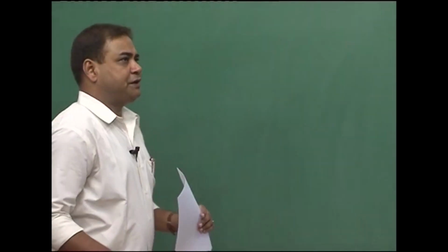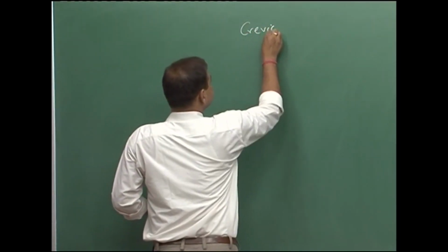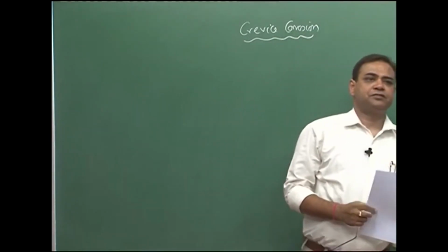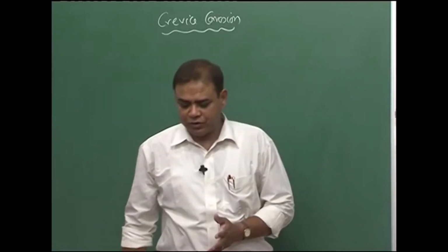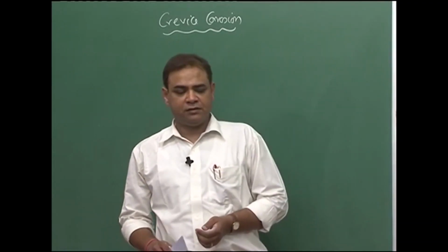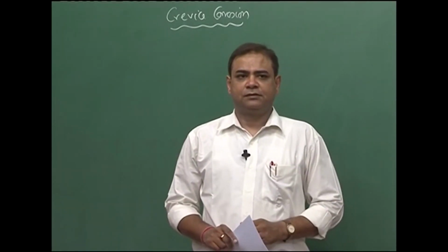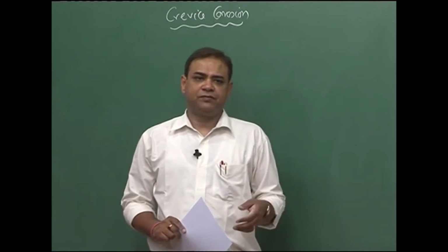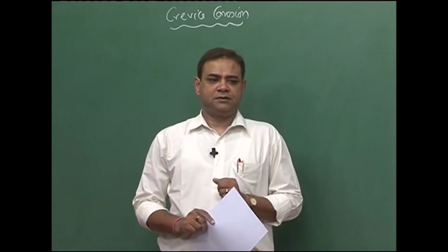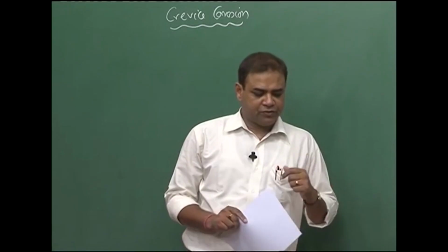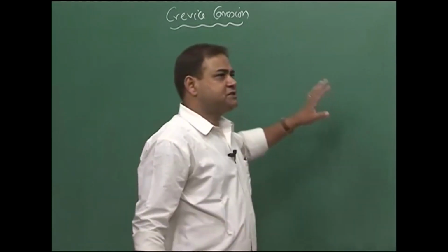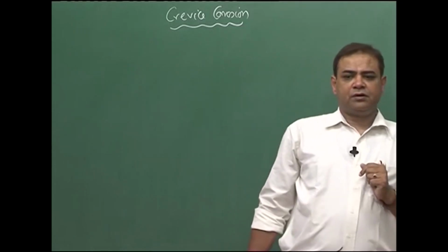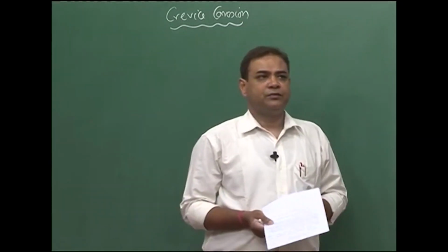Now we discuss crevice corrosion. So, the crevice corrosion is a particular form of corrosion which is highly localized in nature, and of course, there is a galvanic effect that is associated with it because of change in concentration of reduction species, or the species which gets reduced, and this happens in the crevice section of a particular metal or structural object which is under use.